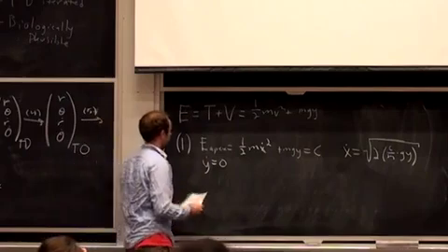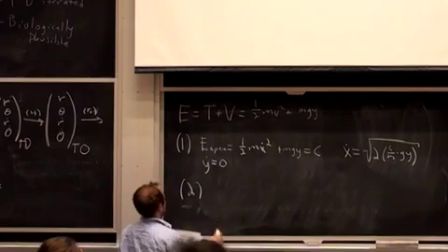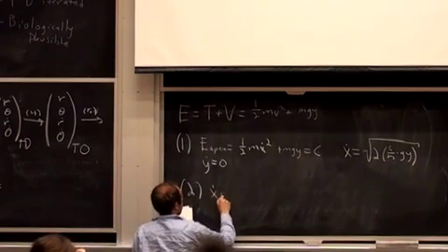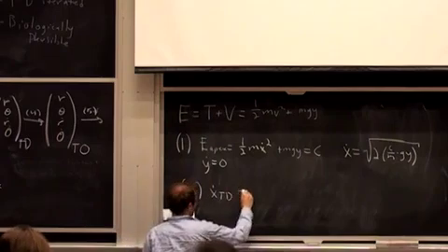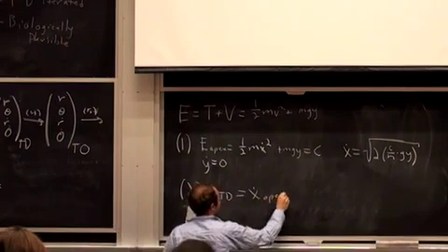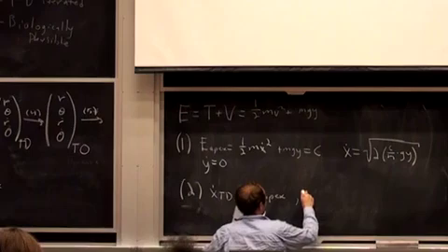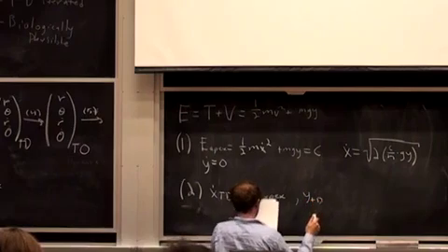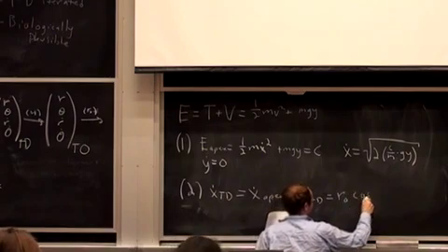Transition 2 then: we know that x dot at touchdown, in the ballistic phase coming down from apex, is equal to x dot at apex, because there are no forces on it, so it's just going to keep carrying forward in x. Then we know y touchdown is going to be r naught cosine theta naught.